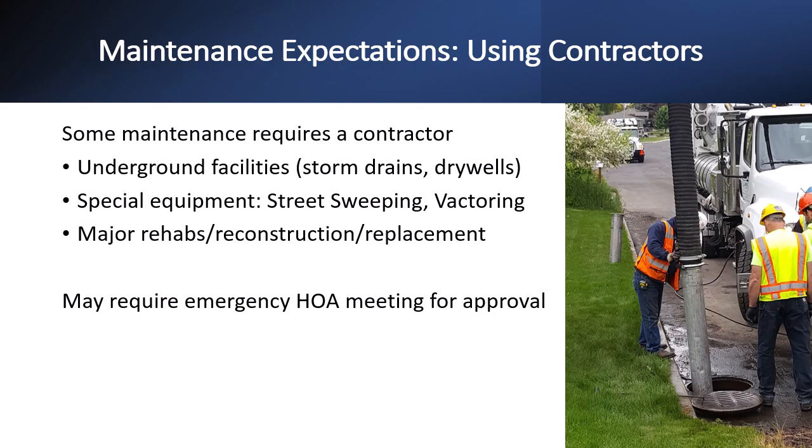Some maintenance activities will require professional contractors. It is recommended to use a professional to inspect and perform maintenance in the following circumstances. Access to and maintenance of underground facilities such as drywells will typically need a contractor due to the requirements for confined spaces, which can be hazardous. You may clean out some storm drain catch basins yourself if they are shallow and can be reached easily by hand tools such as a shovel and shop vac from the surface. Do not climb down into any underground facilities.